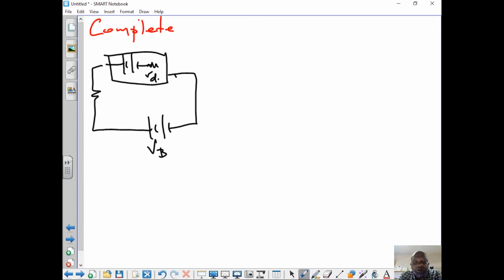VB, and you have R there. You can draw a little equation. You've got this R there. If I want my I forward, that is when it's forward bias like it is here, it would be VB minus V diode. Remember V diode, what is the voltage across it? It is 0.7. The voltage across VD, all divided by the sum of these two resistors, which is your main resistor, limiting resistor, plus the dynamic resistance of your diode.